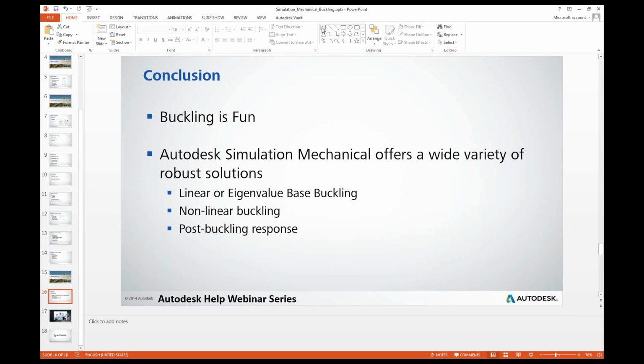And so that's where you may have to play with your mesh size, look at your loading and how you're applying it. You may also have to add more steps to ensure that you're capturing enough information when that transition occurs. So again, I would say yes, but along with doing a nonlinear analysis, you have some other factors you need to consider. The usual considerations, basically. Usual suspects. Yes.